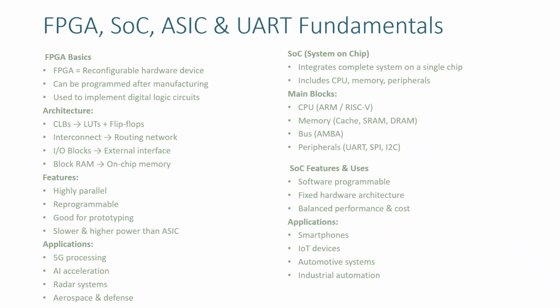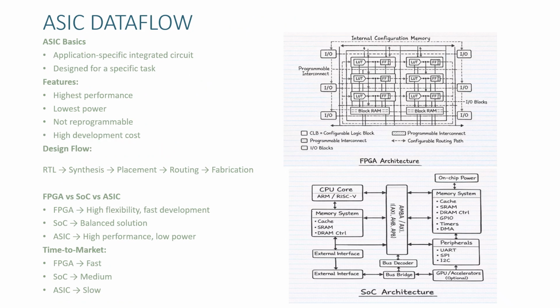Next, I studied different hardware platforms such as FPGA, SoC, and ASIC: FPGA is reconfigurable and ideal for prototyping, and SoC integrates CPU, memory, and peripherals into a single chip. ASIC is designed for a specific purpose and provides the highest performance with low power, but it is not reprogrammable. I also studied UART communication, which transmits data serially without a clock using start and stop bits.